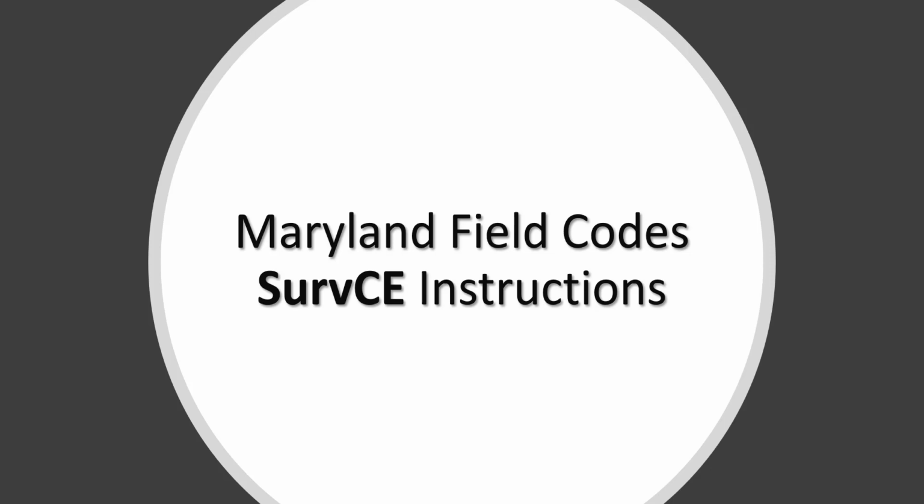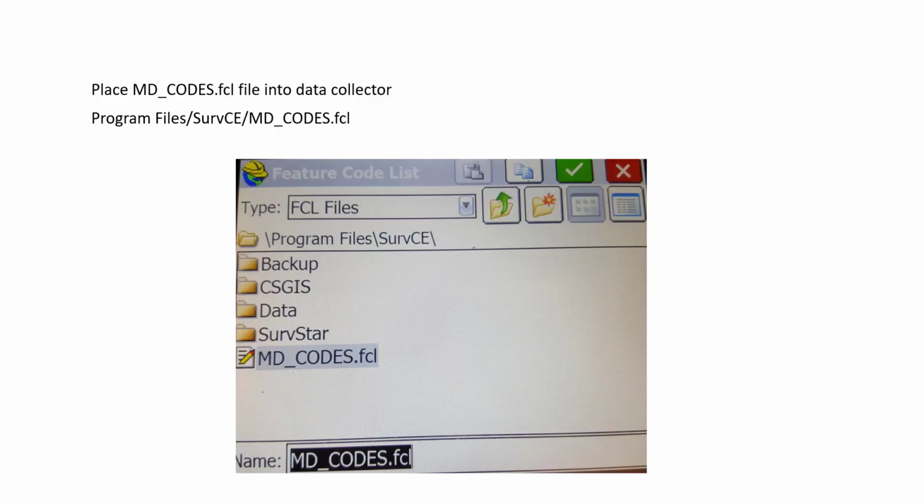So next we're going to get into the Maryland field codes and the SurvCE instructions. So if you're still using SurvCE, these instructions will go over how to enter the Maryland field codes into your data collector. And like I said, where to find those field codes, again, for the state users, they're on the shared drive, and also for NRCS, you go to the shared point.